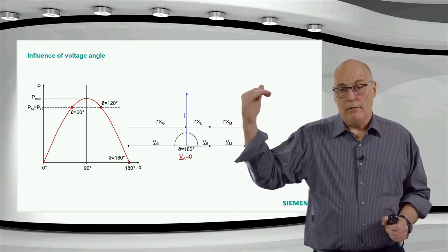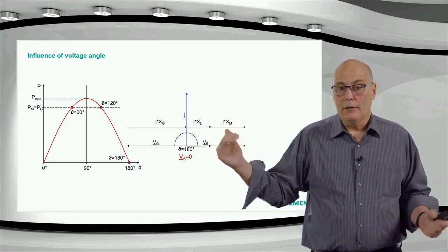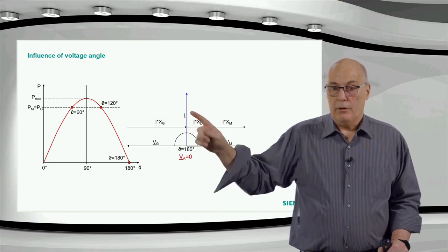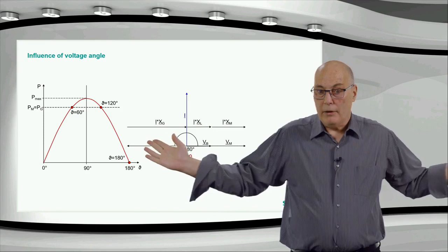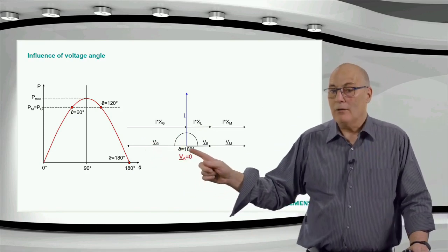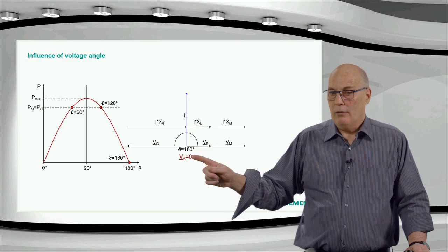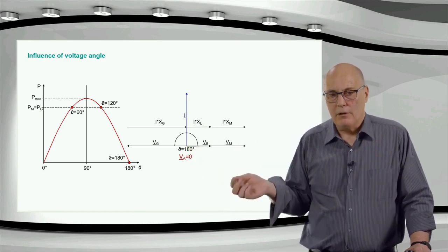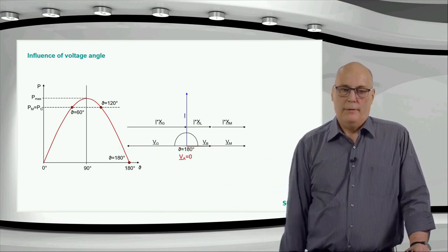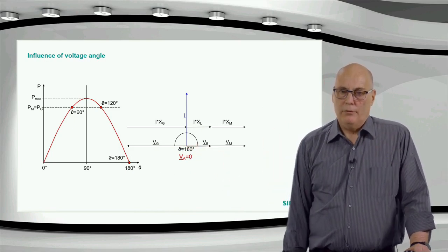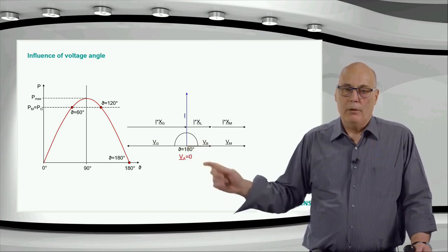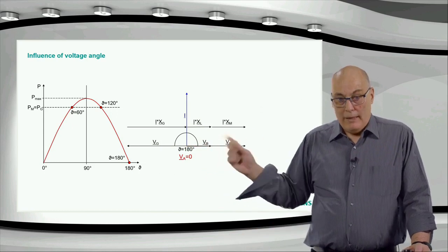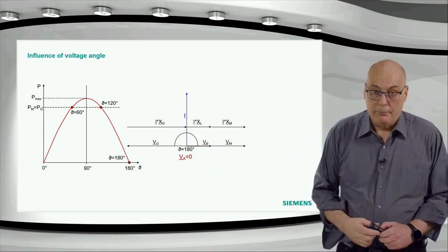Remember, impedance is voltage divided by current. No matter what the current is, current will not be zero. You can see the current is really large, the load current. During the point, the load current has increased a lot because we need a big drop between the left and right side, but the power transferred is zero at the relay location because power is I times V times cosine phi, and cosine of 90 is zero. There's no real power being transferred, only reactive power, VARs. No watts, only VARs at the relay. But the impedance is zero, which is a problem.